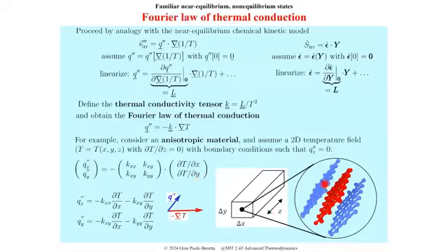And how do you build non-isotropic materials? Well, for example, by sandwiching layers of different materials. For example, you could have a highly conductive layer of a material like carbon sheet sandwiched between an epoxy or some other material with low conductivity. That makes anisotropy.